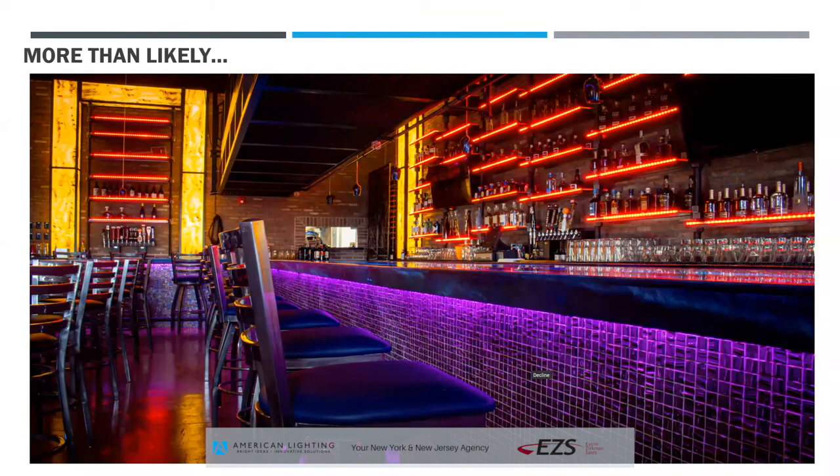When it first came out, a lot of places didn't imagine how you could ever need more than one universe. And now we're looking at Olympics and stuff of that size that are in the thousands of universes. So it's a platform that's definitely grown over time, and that's where the network protocol has come in. If you're ever going into extremely large scale systems, you're going to be transitioning from a hardline DMX into a network backbone infrastructure, which then uses devices to convert the Ethernet protocol into DMX at the actual device level. So when you get into the large complex systems, it just becomes that much more complicated.